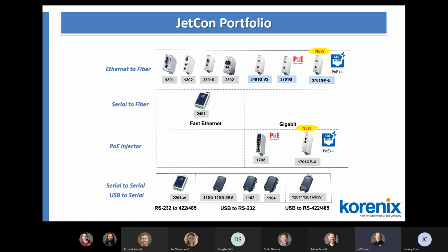Yes. Tony, are you there? Yes, I'm here. What did they say when you talked to them about that? Well, they had conflicting serial ports, and as far as their PLCs go, they didn't have enough serial ports on the HMI to support the controller, and so they needed an Ethernet to serial adapter so they could set up an Ethernet protocol and then be able to access the serial controller.